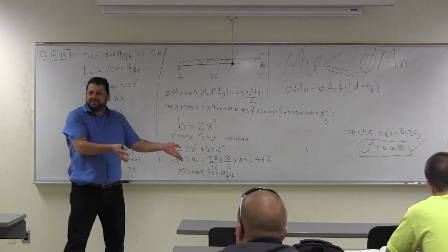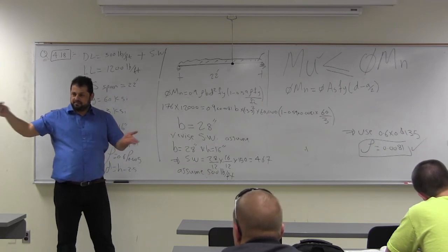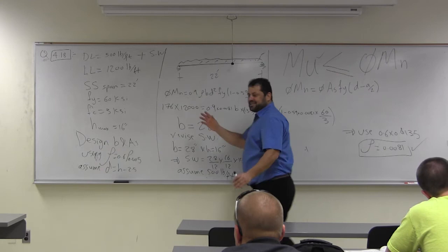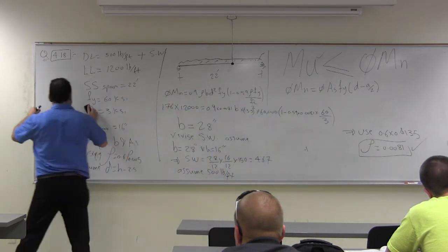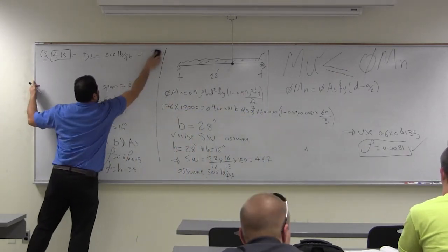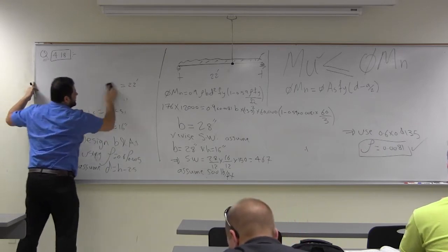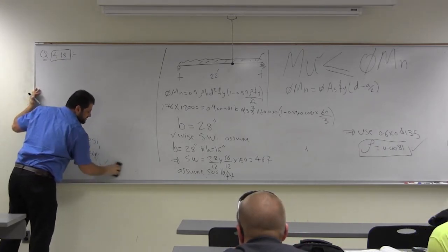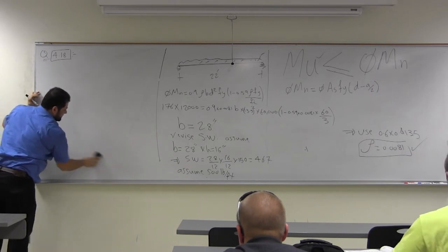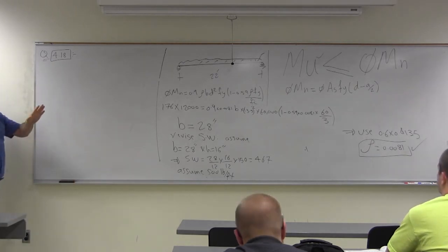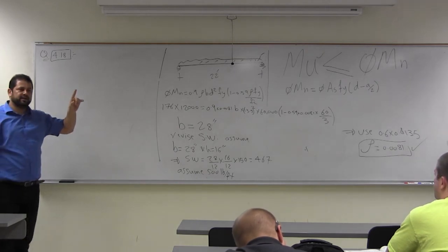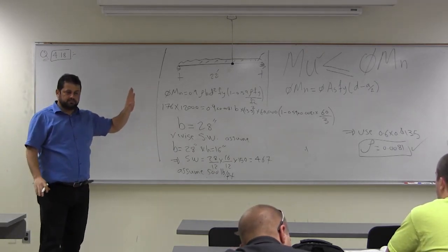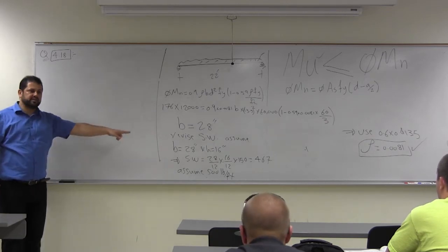If you increase B and D, you decrease the steel. It's a balance. Good? If you are designing with gold or whatever expensive material, okay, just bring it to the 1 millimeter. Remember in the design, I always tell you, as long as your phi Mn is not more than 10% what you need, you're good. So I think we are within the room even if we increase this one little bit.